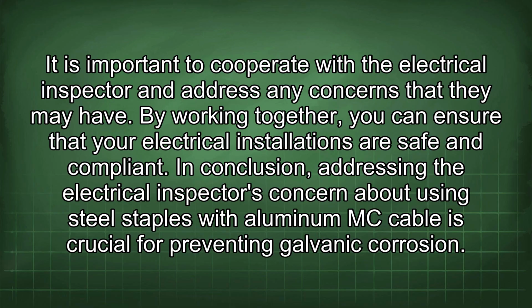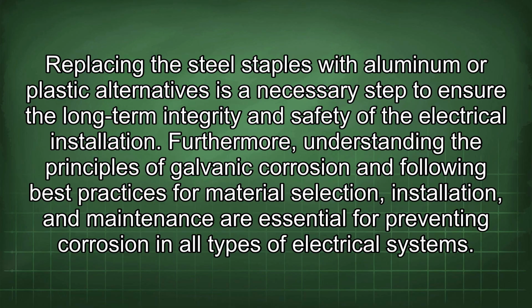In conclusion, addressing the electrical inspector's concern about using steel staples with aluminum MC cable is crucial for preventing galvanic corrosion. Replacing the steel staples with aluminum or plastic alternatives is a necessary step to ensure the long-term integrity and safety of the electrical installation.